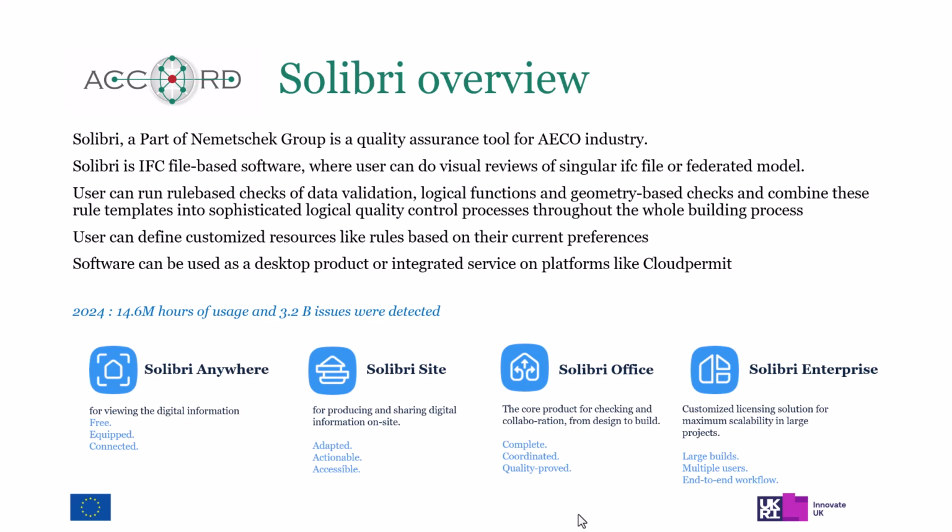Short Solibri overview. Solibri, a part of Nemetschek Group, is a quality assurance tool well known throughout the industry. Solibri is IFC-based software where the user can do visual reviews of a singular IFC file or federated model. The user can run rule-based checks for data validation, logical functions, and geometry-based checks, and combine these rule templates into sophisticated logical quality control processes throughout the whole building process.